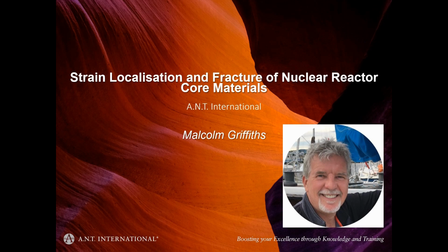That set me off on picking up as much information as I could about the mechanisms of strain localization. It applies to zirconium alloys, austenitic alloys in particular, stainless steels, and nickel alloys. So I'll be talking interchangeably about all three types of materials, zirconium alloys being hexagonal close packed, and the austenitic alloys being face-centered cubic primarily.